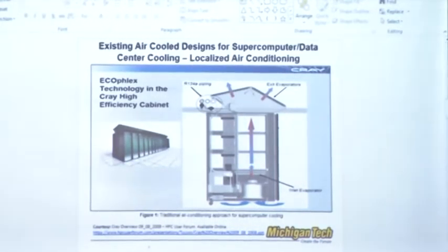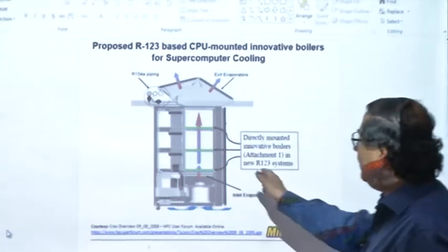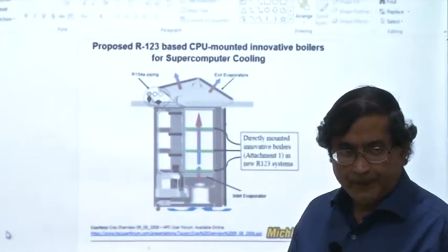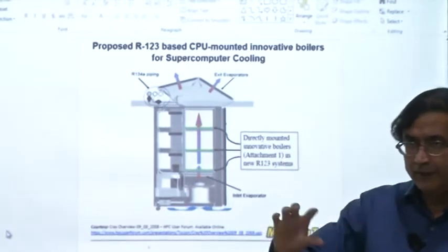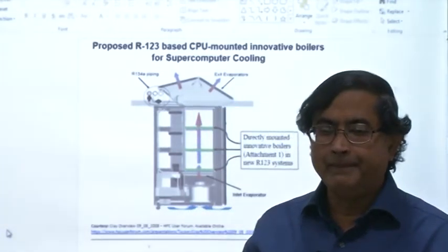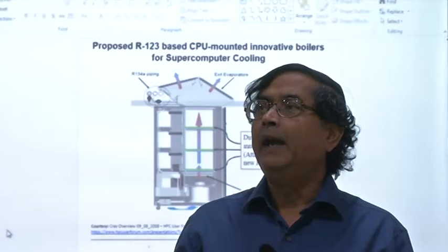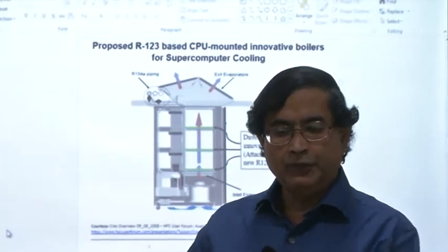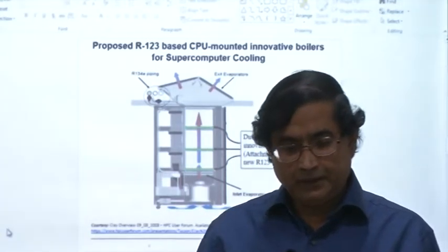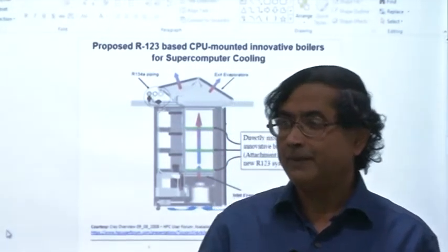So in these situations, if I wanted to replace those flow boilers, from all liquid to all vapor or part liquid vapor, with innovative boilers, the kind that we have in, say, several rectangular cross sections, and suppose I could build each one of them at 50 watt per centimeter square without pulsations, okay? And I had enough length, I knew my incoming mass flow rate, outgoing mass flow rates. I can, by dialing in pulsations, go from 50 to 500 watt per centimeter square.